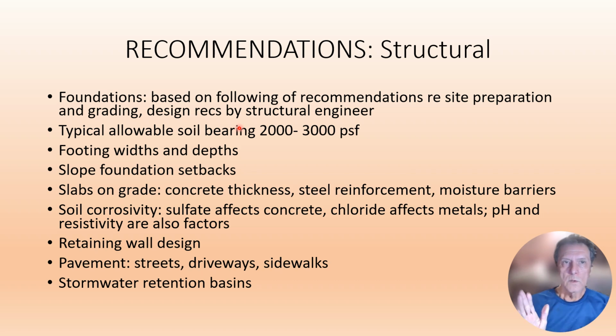In your report, you want to include structural recommendations for the actual buildings, construction, foundation types, soil bearing pressures, footing dimensions, any setbacks from slopes. Typically, you don't want to have a foundation right at the edge of a slope. You want to set that back away from the slope. You want to give recommendations for slabs on grade, concrete, steel, moisture barriers, etc. Want to discuss soil corrosivity. Maybe your site has soils which contain a lot of sulfates and chlorides.